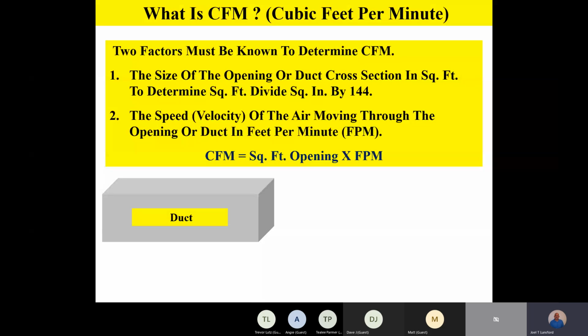And then we're going to measure the velocity of the grill in those test areas, and then add those velocities up and divide by 6 in this example to get an average velocity. So clear your calculator for me, and we're going to find the average velocity across this grill or register by taking multiple readings.